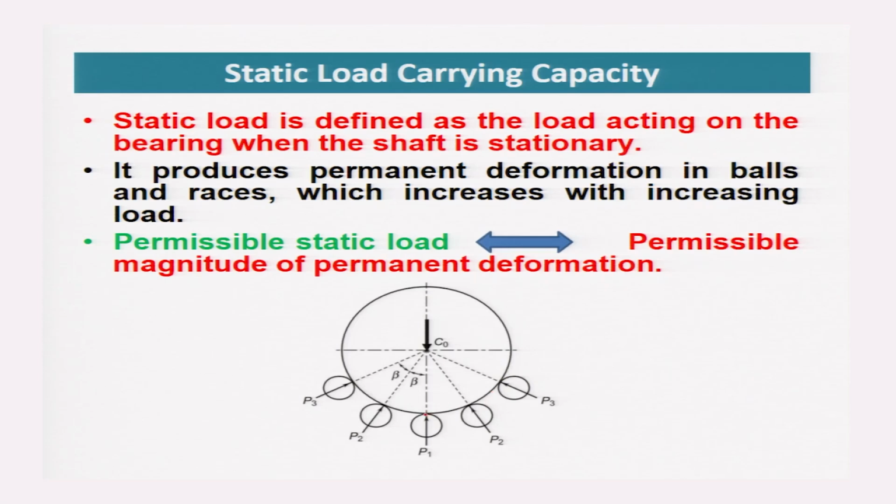It produces the maximum load carrying capacity. Under that condition, permanent deformation in balls and races is produced, which increases with increasing load.